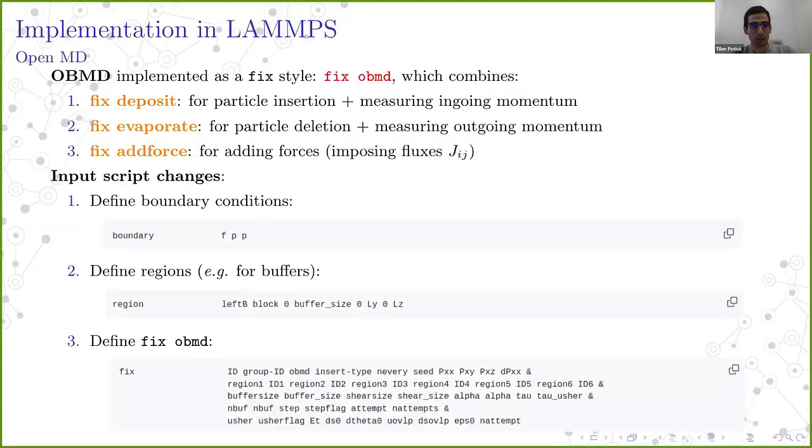And to go a little bit into the detail of how we implemented this Open Molecular Dynamics. We combined three existing fix styles in LAMMPS. LAMMPS has these famous fix styles, which are typically either integrators or some on-the-fly statistics. And we combined three of them: fix deposit, which is for particle insertion and measuring ingoing momentum, fix evaporate for particle deletion and measuring the outgoing momentum, and fix addforce for adding the forces.